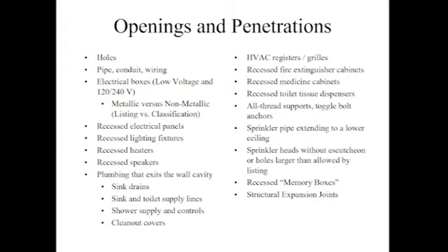Things like recessed electrical panels. There's no such thing, not that I have seen yet. I would love somebody to show me one of an actual fire rated electrical panel board that's classified for installation in a fire resistive assembly. I haven't seen one yet. And so I'm not talking about the 4x4 boxes, but the actual electrical panels, the big stuff. At this point, everything I can see needs to be surface mounted on a rated assembly and not recessed.